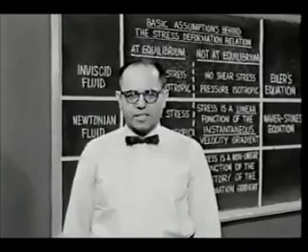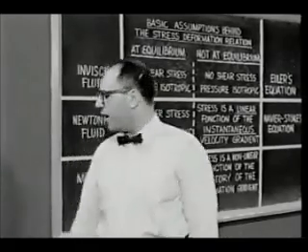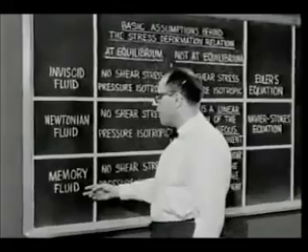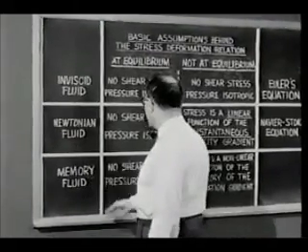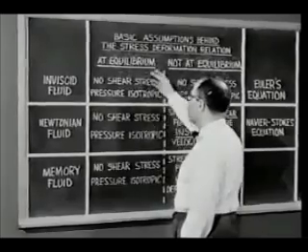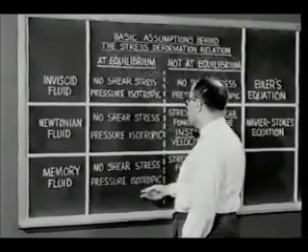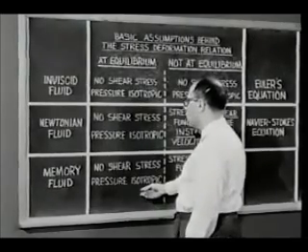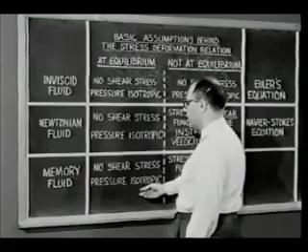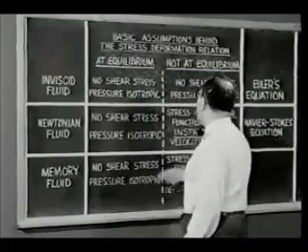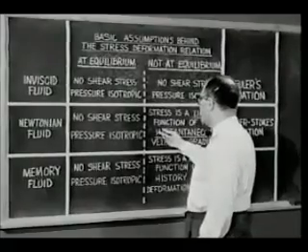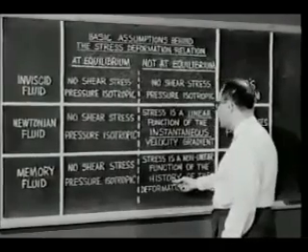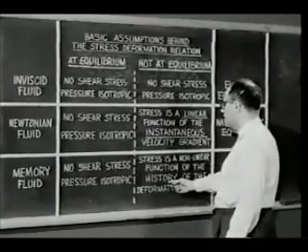For many of these, a more general model, that of the memory fluid, does provide an explanation. For the memory fluid, the pressure is isotropic in the equilibrium state where no changes of either the stress or the deformation are taking place. In relative motion, however, in contrast to the Newtonian fluid, the history of the deformation is significant.